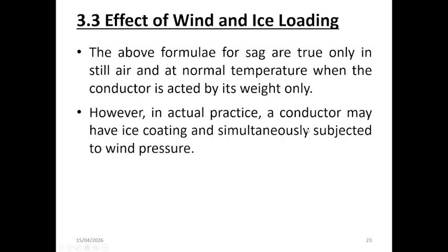This is a new subject. This slide highlights the limitation of the basic sag equations and introduces more realistic operating conditions for overhead conductors. The standard sag formulas assume still air and normal temperature, where the conductor is influenced only by its own weight.